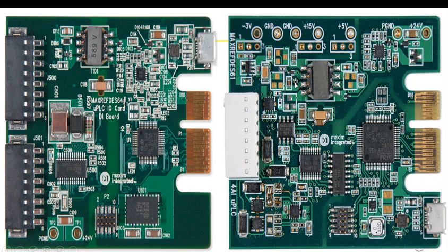Okay, so as you can see, this is having a lesser circuit as compared to this analog input module. The reason I have told you why, because the analog signal must be converted into the digital signal. Okay, so just for that purpose, that's why the cost of analog input module is also higher than your digital input module. Okay, so this is a 4 analog input card of the PLC. So this is indicated on the card.